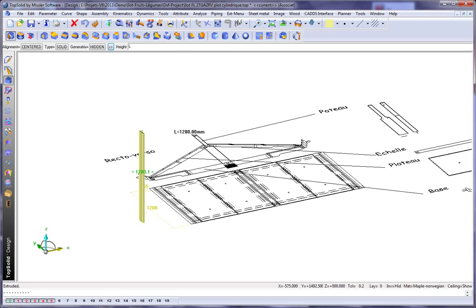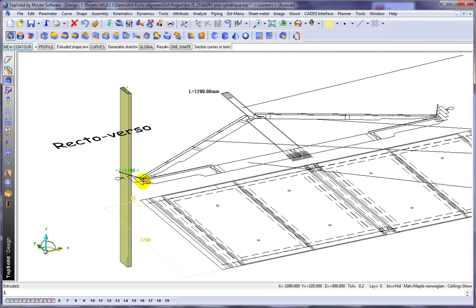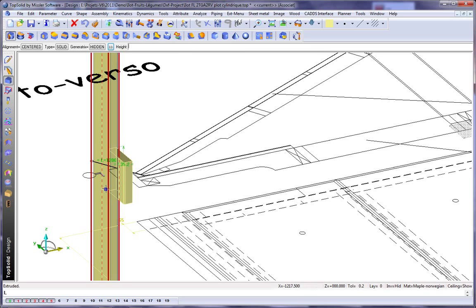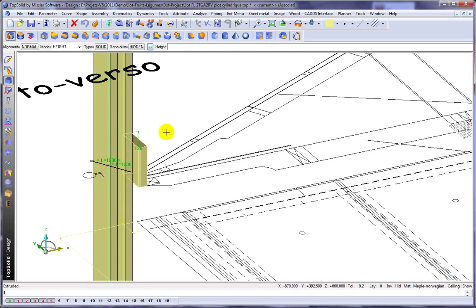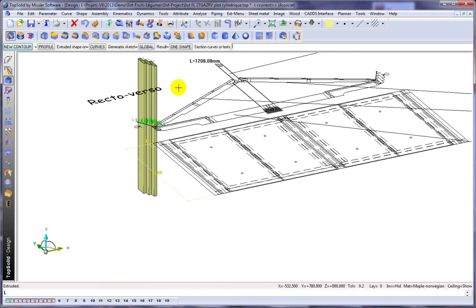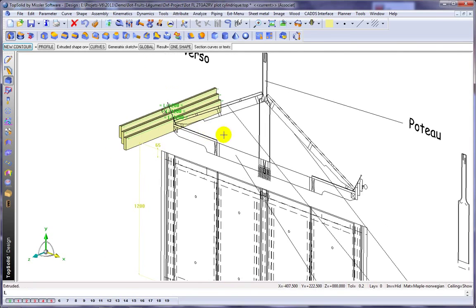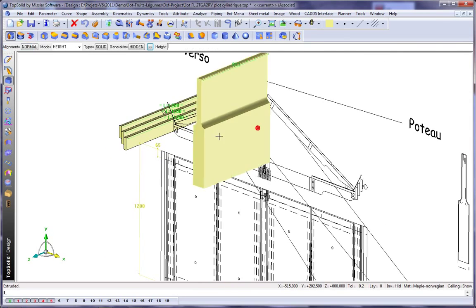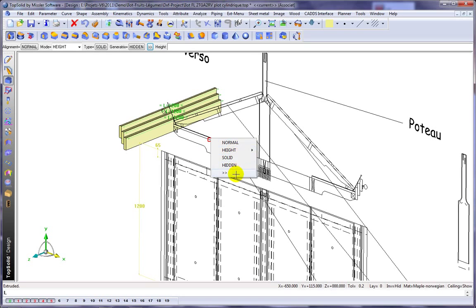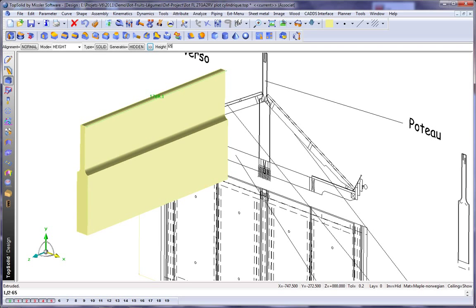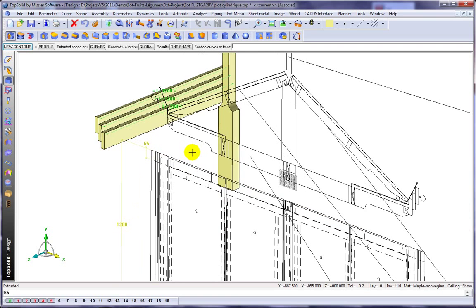Here we're going to make it a centered extrusion and make it equal to L. And we'll do the same thing here. Centered equal to L, centered equal to L. Perfect. Now let's take that profile, and we're going to offset its start position to be half of L minus 65 millimeters, and then we're going to extrude for 65 millimeters.